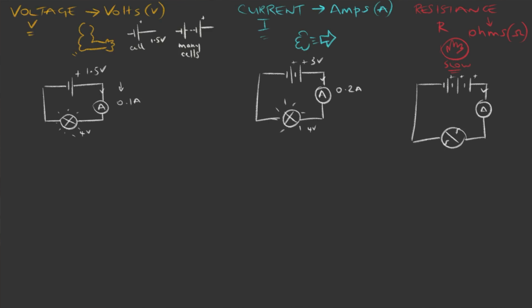To make the bulb light up at its brightest, we could use the 4.5 volt battery and add a fixed resistor in series with the bulb to drop the voltage going through the bulb to 4 volts. But we still have one big problem. To calculate the size of this resistor, we first need to calculate how much resistance is being made by the light bulb. To calculate the resistance, we can use a very simple equation called Ohm's Law.